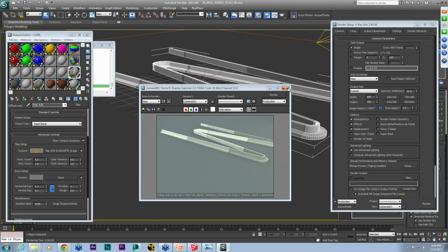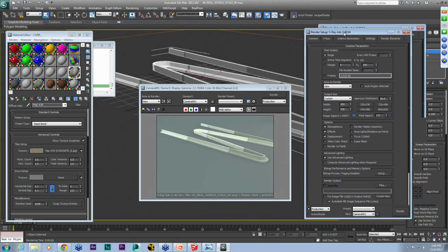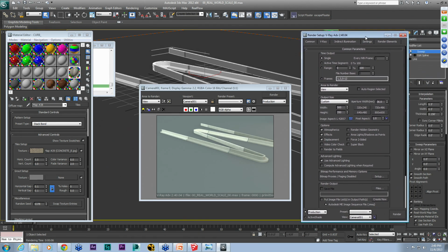So very quick way to use real world scale. Another good thing about real world scale is that you can apply it, again, like I was showing with those layers. If you have an instanced real world scale map, you always know that all of your objects, because when you select a layer, they all have the same instance map. You'll see the instance map pop up in your modifier panel, and you know that everything in that layer is mapped correctly, and that the size is all correct because you have it based in the material and not in the actual modifier. So it's another sort of quality control check, to make sure that you're not getting random scales on things like you would with different UV maps in a scene.